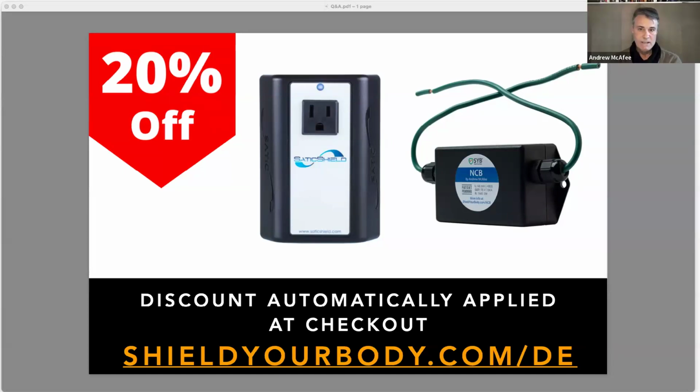This is really a complex topic. If it's a backup generator, is it feeding the whole home? Is your wiring in your home all Romex, so no shielding at all? Yeah, it's going to be a disaster. So the house has to have shielded wiring to contain these frequencies, so you can only deal with certain loads, certain breakers that are critical during a crisis, your refrigerators, and try to keep the loads out of your sleeping areas. Just keep it where you need it.